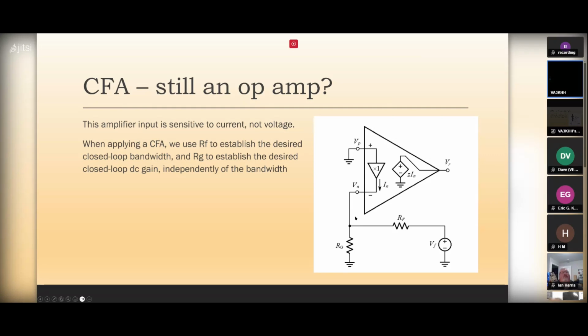And you use these two resistors together to set the gain and the bandwidth. And one of the differences of this amplifier versus the standard 324 or 2323 op-amp, the standard voltage controlled voltage source, is that to make the standard op-amp stable, they put a capacitor in there. So it's got a single pole filter. And that capacitor is what gives you your gain bandwidth product.